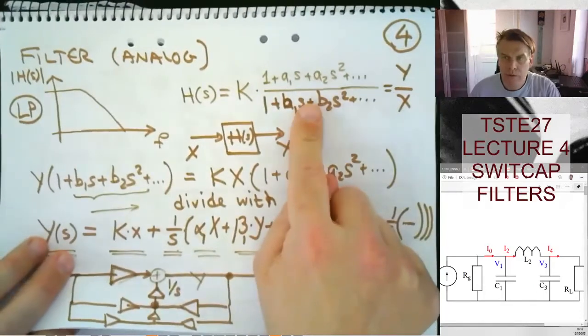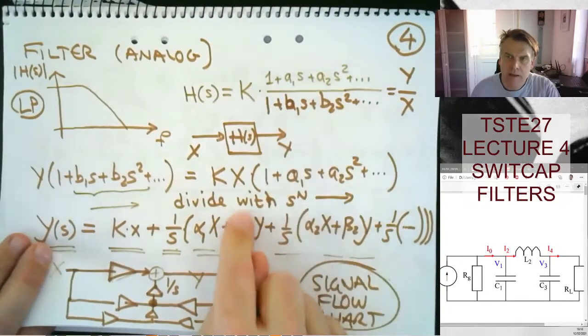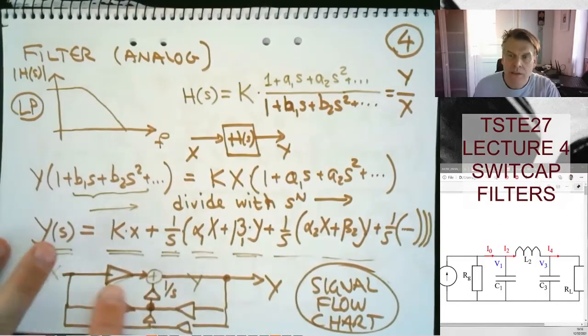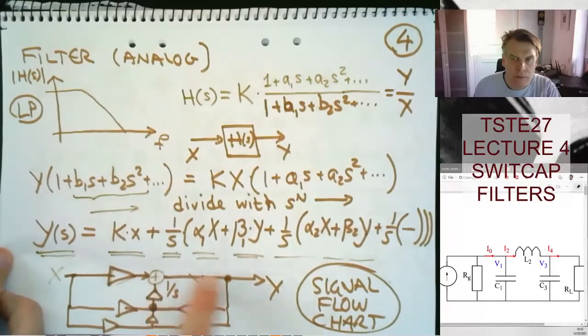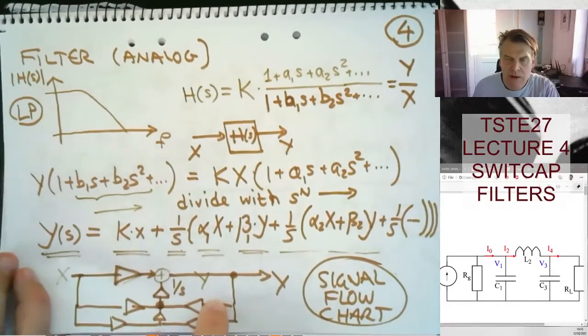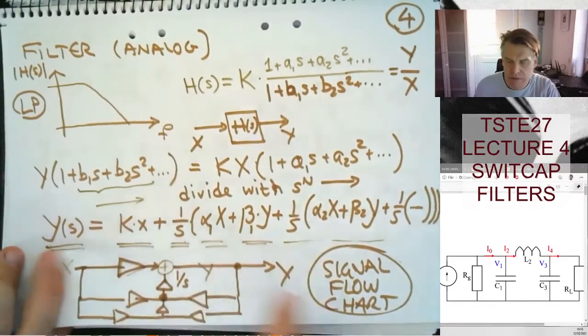We could do that also here, but one of the problems is that there is a cascade of integrators, like down here. You have a set of integrators, which means that certain signals have to pass through the entire chain of integrators. So this structure has a certain sensitivity to potential errors in this long path.